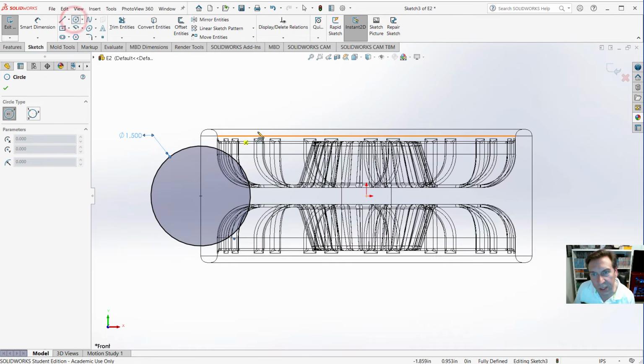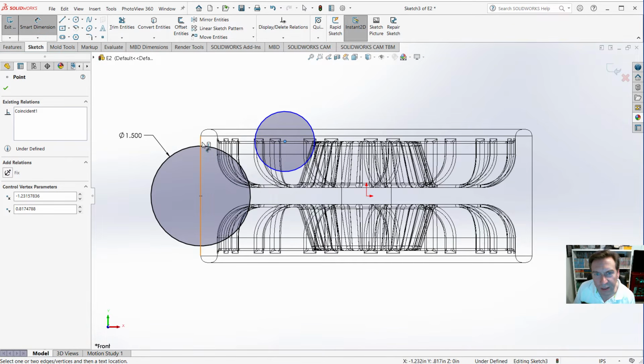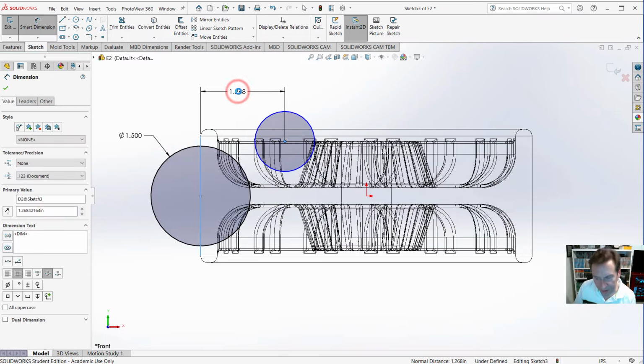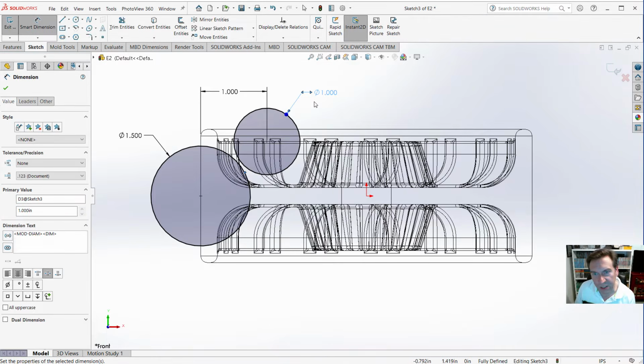Now go to the circle tool again, and right up here, well actually this is where our rib is. Don't get the midpoint of that and stay away, like kind of get it close to where I am at, if you could eyeball that. And I'm not liking exactly where mine is. In fact, it's probably too far, but that's okay. We'll add a dimension. Select this point to this edge. And let's see what 1 inch does. Yeah, that's pretty good. Now, if yours gives you an error and it says it can't do it, delete your circle and just redraw it. Make sure it doesn't lock into anything other than an edge. All right, and then we'll make this 1 inch in diameter.